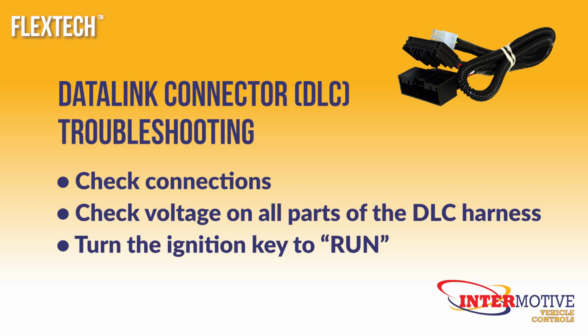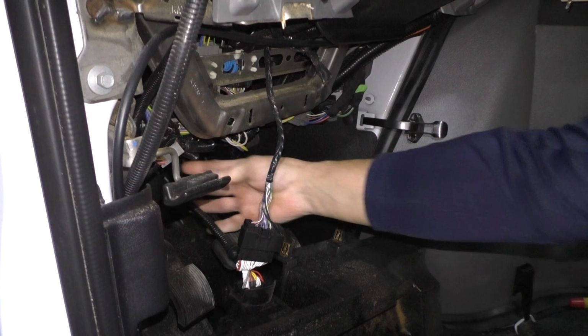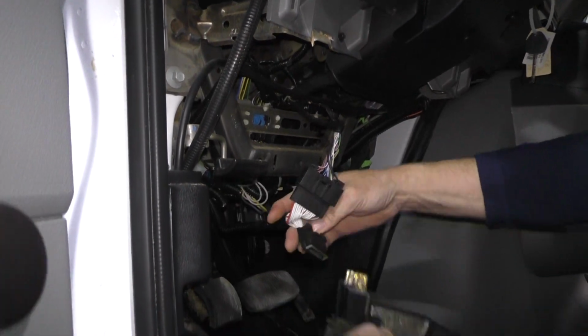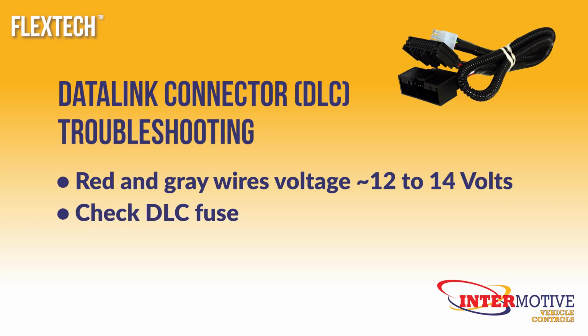To check voltage, turn the key to the run position and verify proper voltage starting at the DLC connector on the PRPC, the DLC-T harness, and then the DLC connector to the OBD2. The voltage across the red and gray wires will be battery voltage, approximately 12 to 14 volts. Also verify the chassis DLC fuse has not blown.